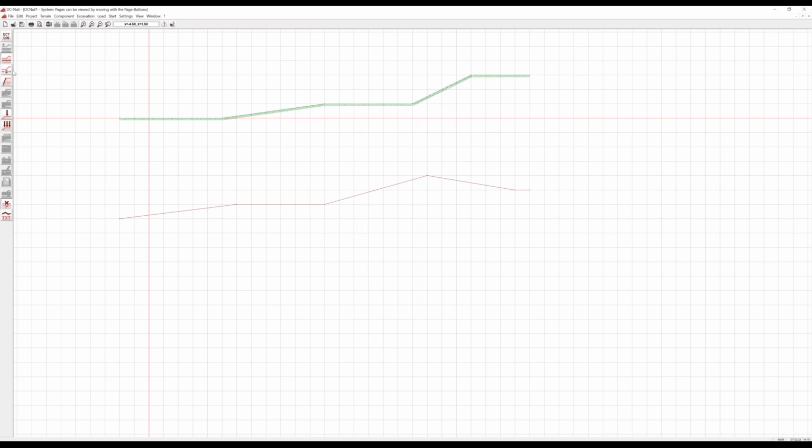We can define a water level in the ground. And then, if we have an excavation at this side, we define the shotcrete wall, which holds the surface here and which is fixed by the soil nails. So I can enter the wall here. Mostly it's inclined, for example, under 80 degrees. And these can also be several sections, or I finish this with the right mouse button.